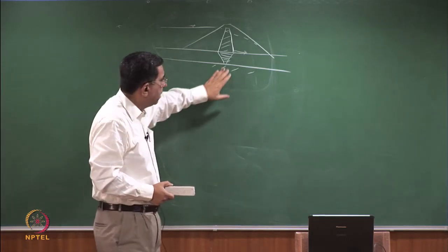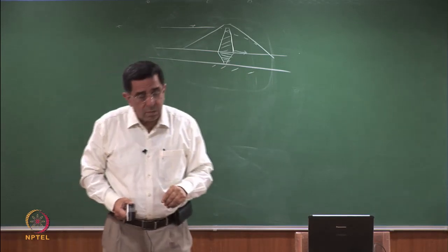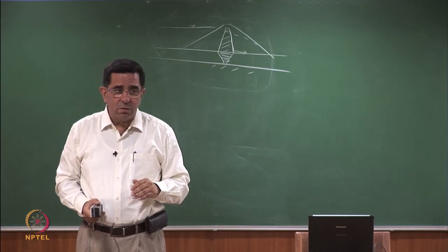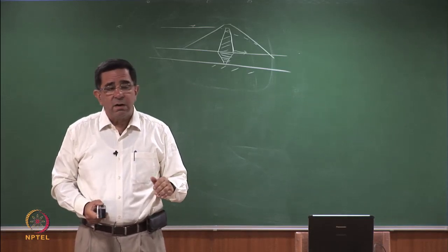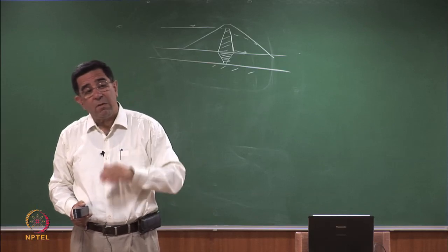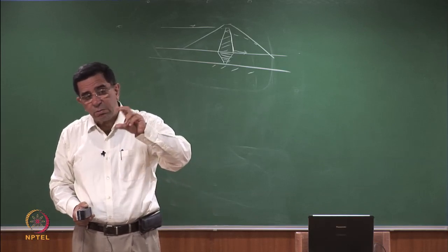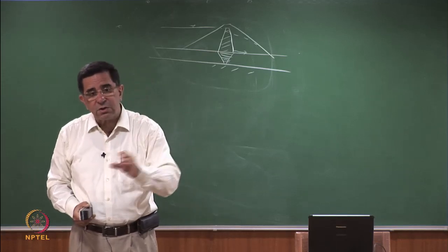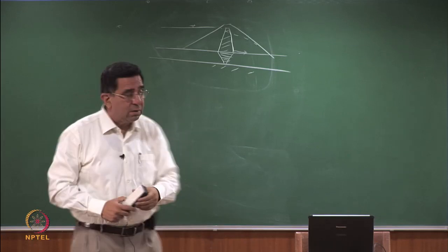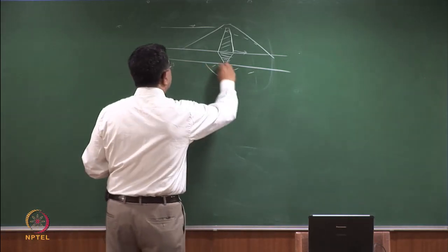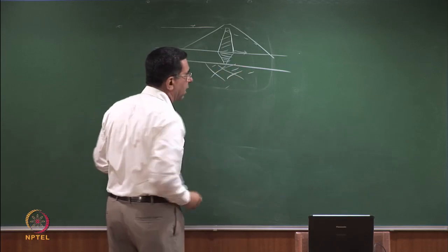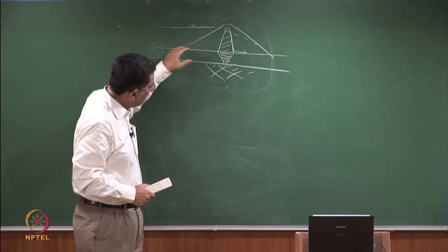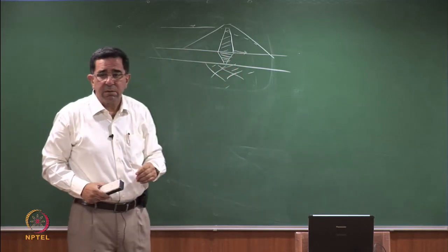Is this rock going to be impermeable? Is soil likely to be underlain by impermeable rock or more fractured and disintegrated and then later on competent rock? So most of the interfaces between soil and rock are not hard rock. They all have joints and fissures and they are pretty permeable. So you will have some kind of jointing pattern and then this will be competent rock at the bottom. So if I stop the water here and if I stop the water here, water still wants to go through the rock. So what do we do?